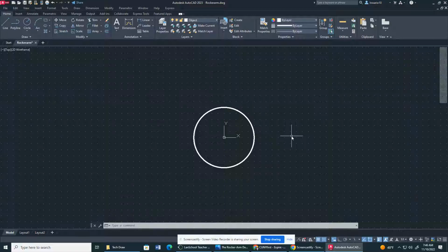Now, I'm going to show you another way how to add a circle. So the first circle has to be 70 millimeters to the right and then 40 millimeters upward, right? So to do that, we're going to click circle. Now, if you see on the cursor it says specify center point for circle, that means we can click or we can type it in. So we're going to type it in. So our X value is going to be the one that's highlighted first, right? So as you see here, negative 160, we're going to change that to 70.